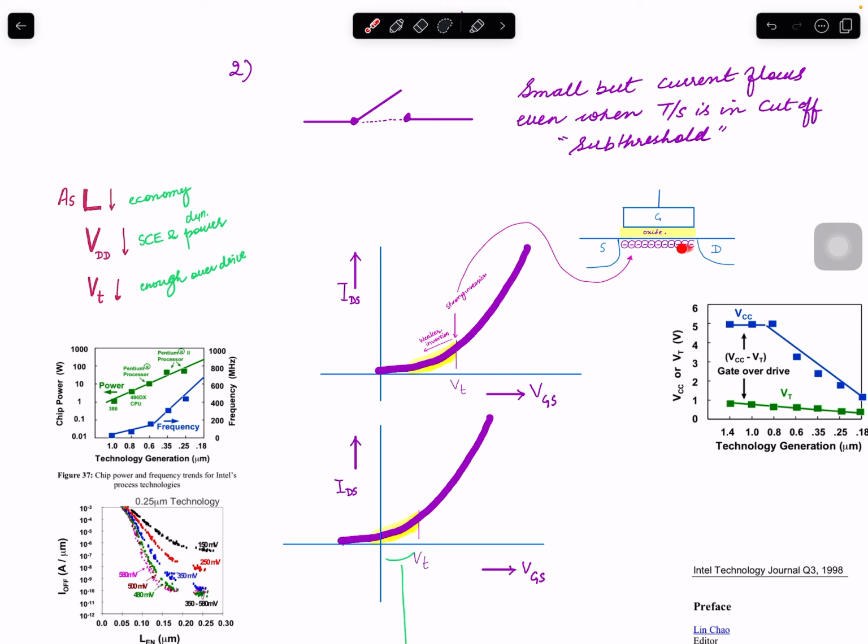In this case, the CMOS transistor has gate, source, drain, NMOS. The channel is created here. Through the gate voltage, we can control when this channel is created, and then through the voltage here, we can push the current flow. When we don't want this current, we don't have enough voltage, or less than VT voltage, if you remember. Then it's off.